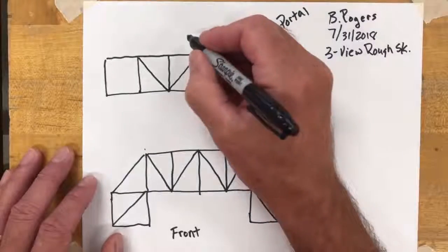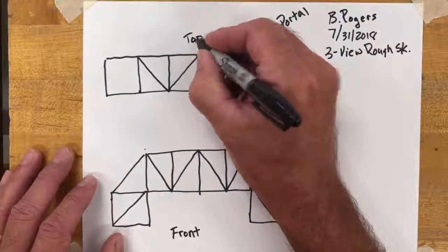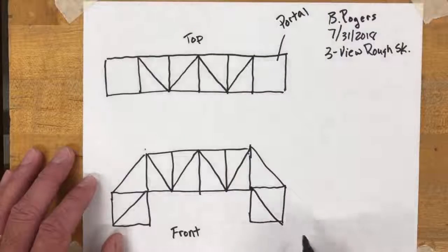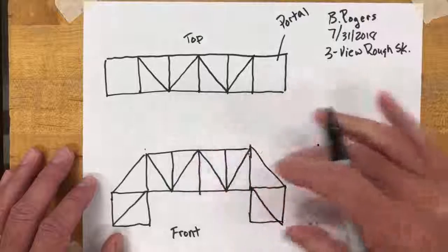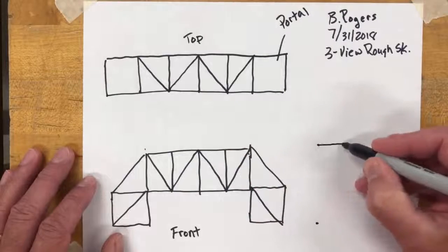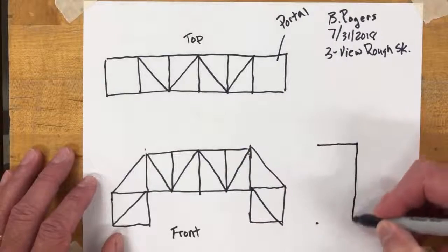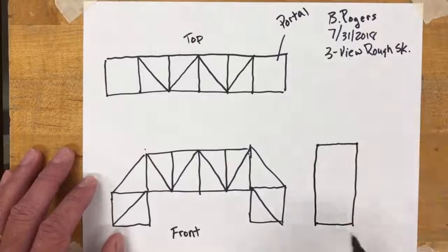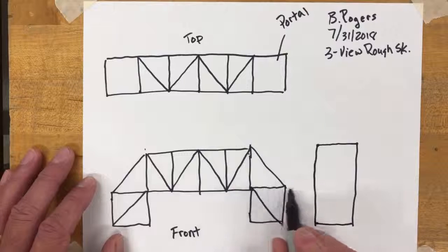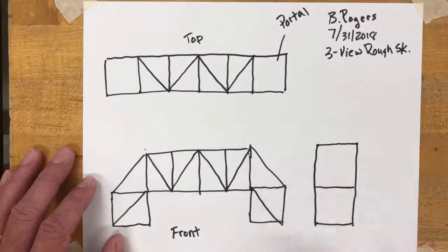So I think I'm going to go ahead and label that top view for now. Start working on my right side view. Once again, I'm projecting over a couple of points right in line with my front view. I'm going to go ahead and estimate how wide this is going to be in the right side. And so I end up with a rectangle that looks like that. There's my roadway, so I'm going to go ahead and put a roadway in there.